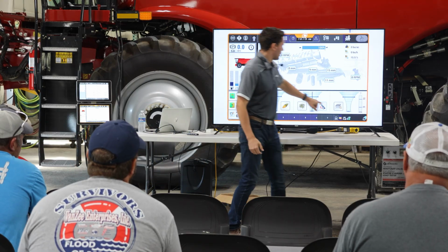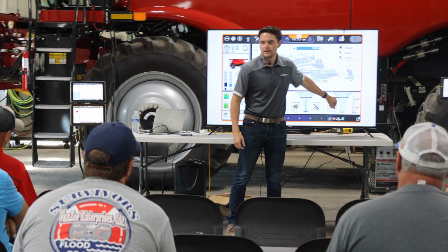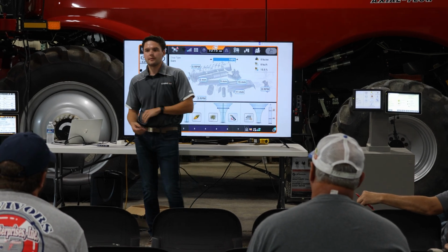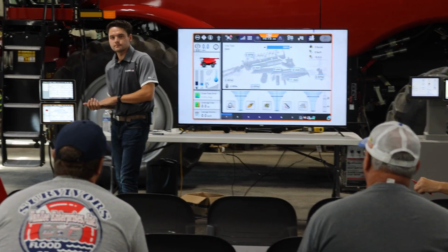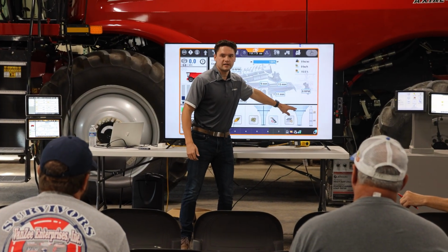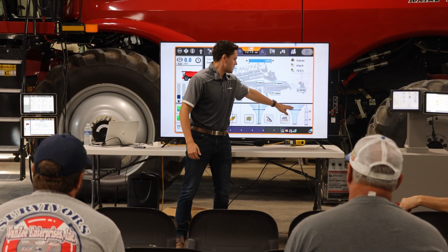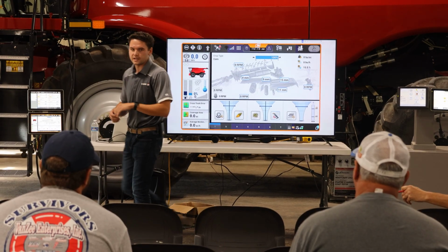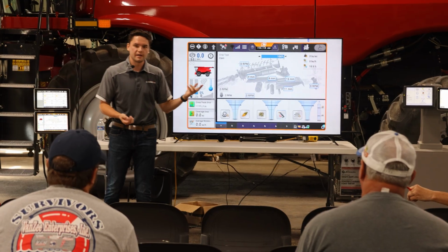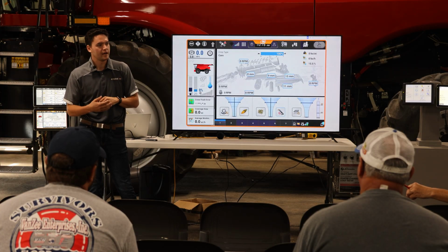So if we're running along here and we're running as low as possible, and I just said this is a trigger point, right? Our trigger point is 3/4 of fill right here. What needs to happen before the combine will make a change? Trigger point. So it needs to fill all the way up to here, then crest this before it'll make a change. So in some scenarios, depending on our adjust frequency, that could be a minute before it even makes a change. But what if it takes 4 or 5 minutes to even get to the trigger point, and then another minute to actually make a change? That's 6, 7, maybe 8 minutes before it actually did anything.